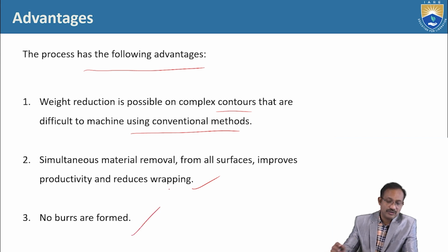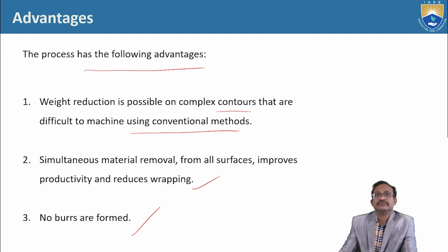Third one, no burrs are formed. Usually because of single point or multi point cutting tools, burrs will be formed even after the machining process. Sometimes in conventional methods we have to remove those burrs with different techniques, but here there is no question of burrs.